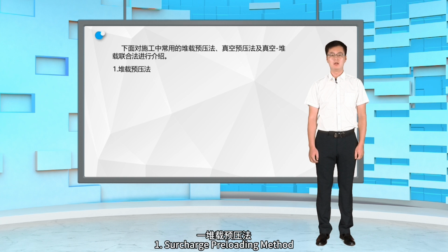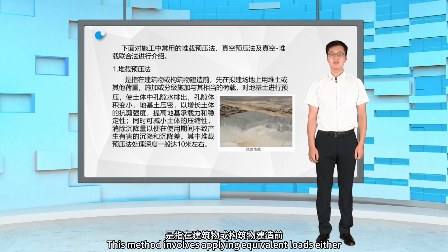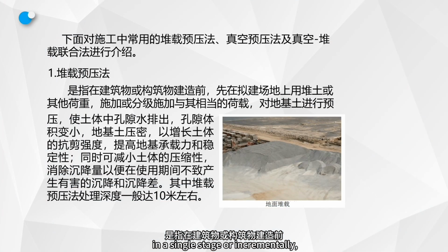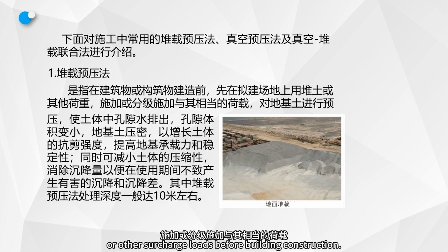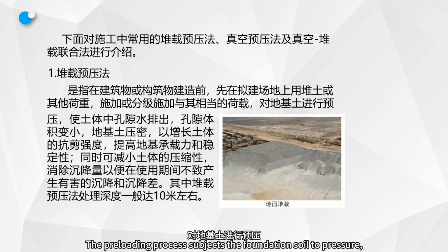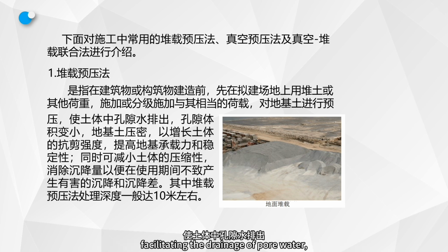First, surcharge preloading method. This method involves applying equivalent loads either in a single stage or incrementally to the proposed construction site using earth fills or other surcharge loads before building construction. The preloading process subjects the foundation soil to pressure, facilitating the drainage of pore water, reducing pore volume, and compacting the foundation soil.